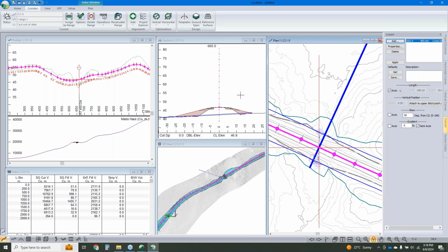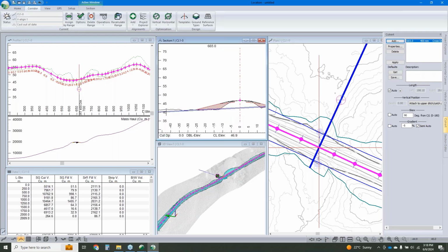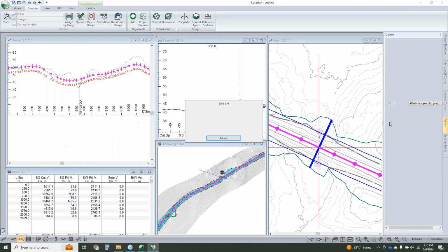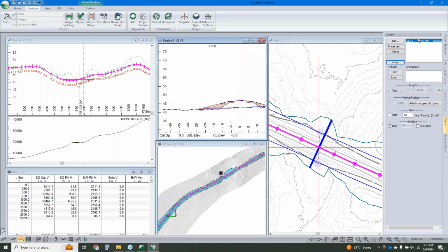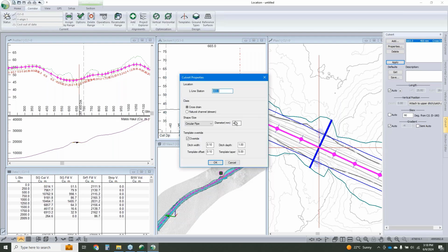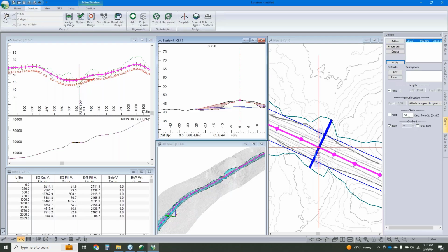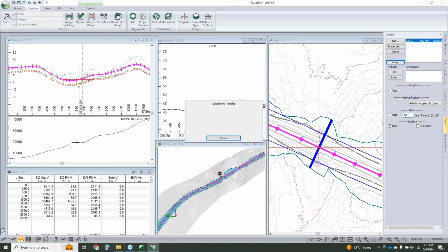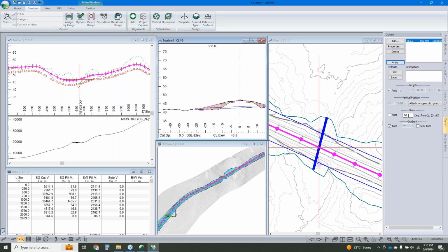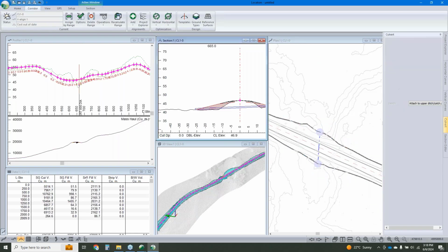Now that is extending on through my topo, so I want to match the crossfall of my existing ground rather than using a 5% drop. We'll change our size to whatever we'd like. And we can tweak our skew if we'd like here too.